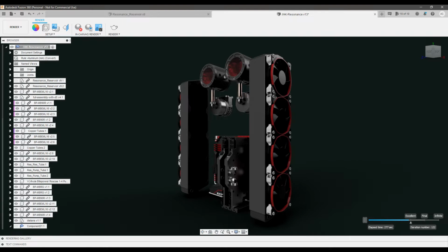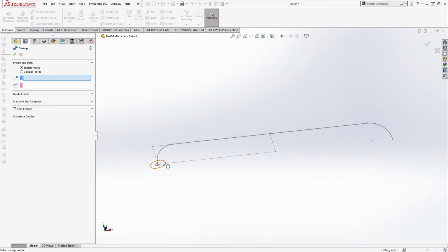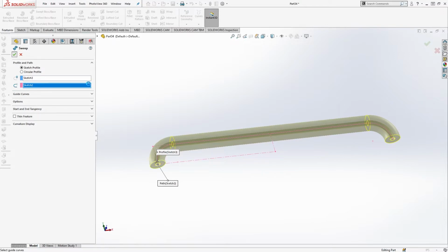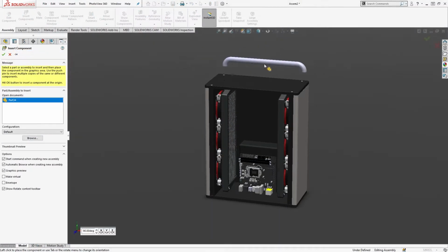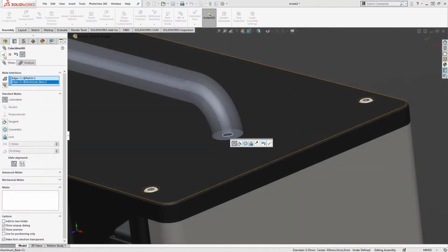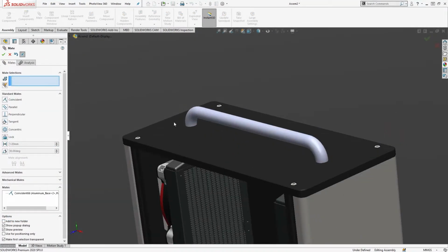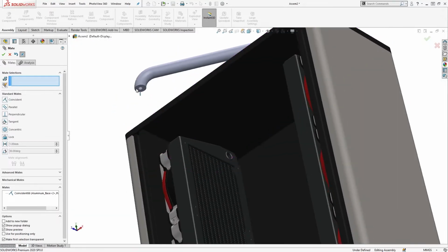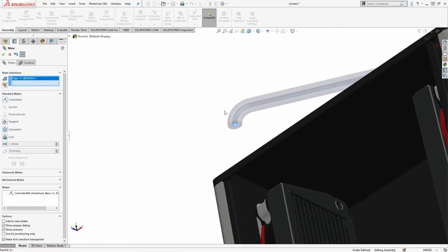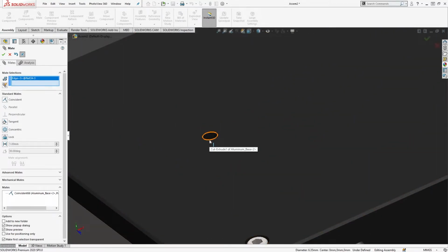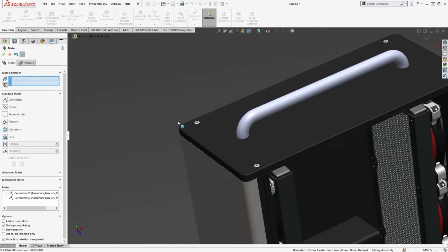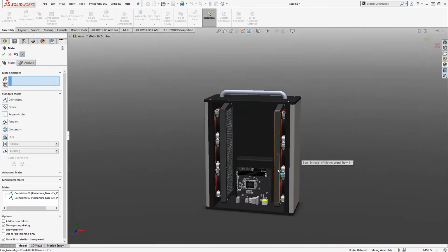In 3D design, there are really only two primary schools of thought, bottom-up or top-down design. The conventional method for most 3D programs is bottom-up, which means that you create each part individually in a separate part file, and then bring them all together into an assembly file in which you can create relationships between components by joining or mating them together. This is extremely useful when dealing with complex designs or large assemblies, as our program does not need to recalculate every part in your assembly each time an individual part has been modified, but merely change its position in space.